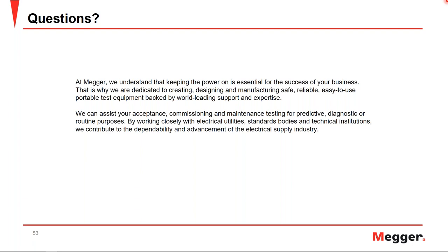All these come into play, and it's impossible to get a transformer in the same condition to test every time. So rather than having the transformer in the exact same condition every time, you translate the measurement that you received into a 20 degrees C value. That way it improves your ability to trend those results and compare them down the line.